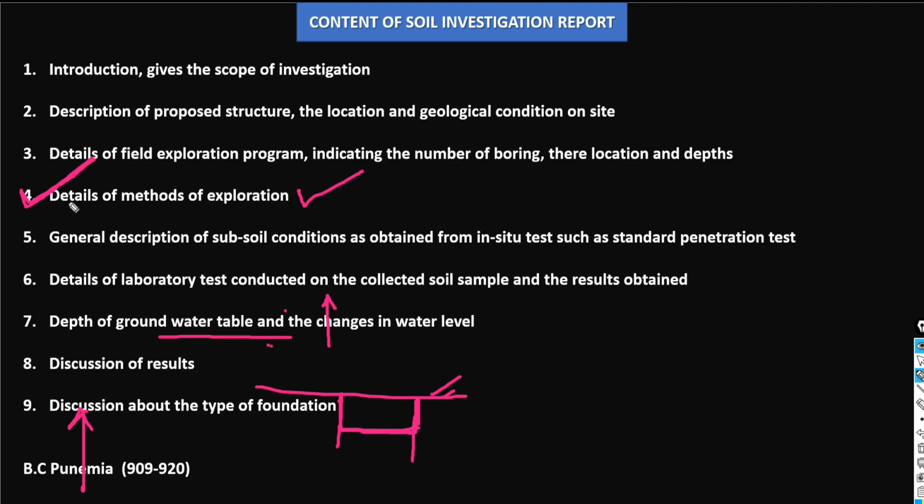After getting all the preliminary properties of the soil, there will be calculation. After the calculation, they will get the important capacities: shear capacity, bearing capacity, net bearing capacity, ultimate bearing capacity. All kinds of capacity of your soil will be given in your investigation report.